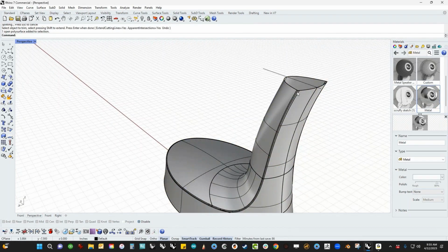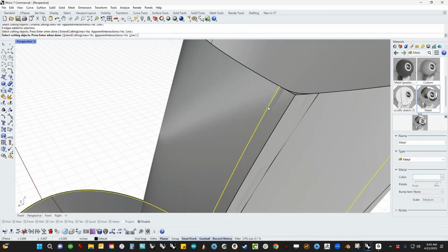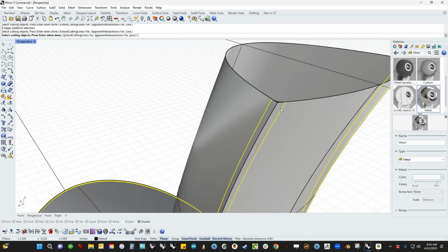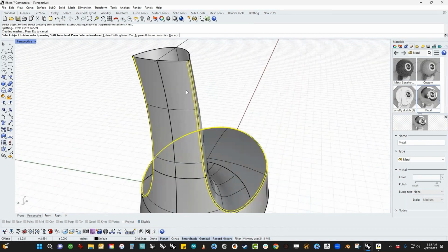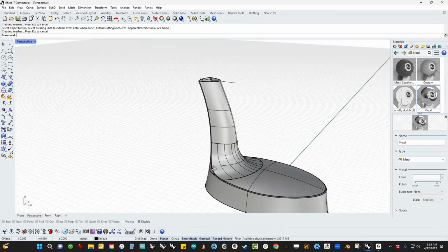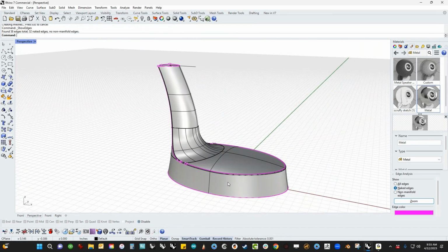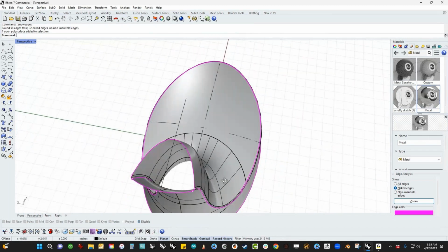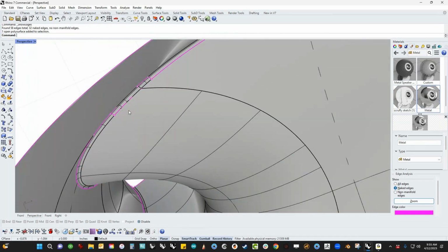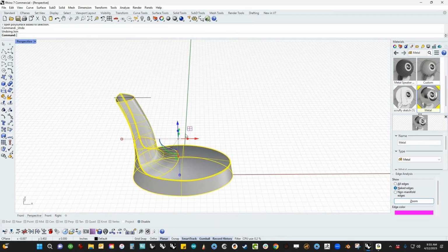And what I find is that you can go through and do this, and we can actually trim, just to prove that we can do it. If I trim and then I type CRV, we can use curves to go back and trim this stuff, right? And it will actually trim and it will actually go together like that. And if we join it, it should look all right. See what our naked edges look like. It does look like it's got a bunch of naked edges because we didn't trim. Looks like there was still some stuff down here that didn't trim. So that's kind of a hassle, right? So let's back up and let's do it a different way.